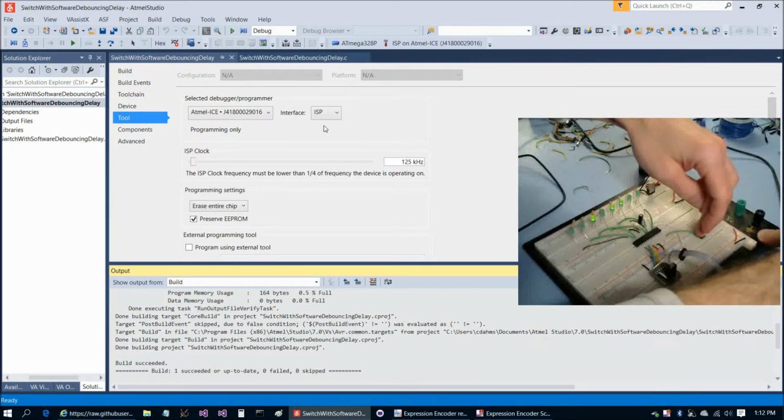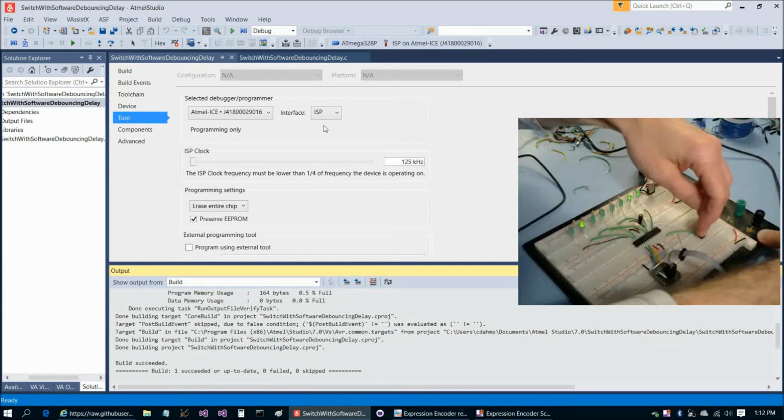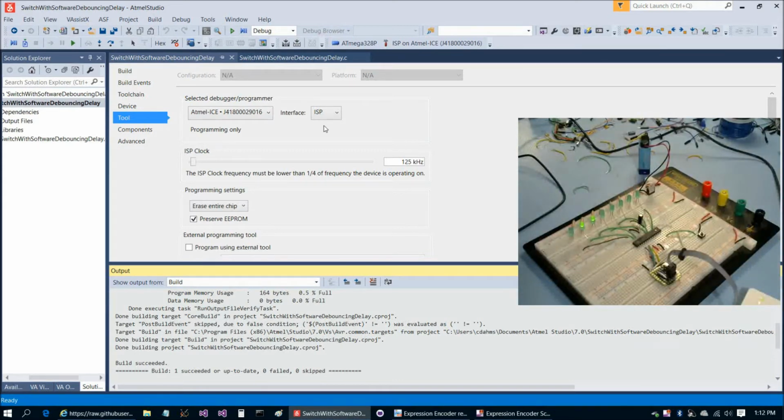So if you're willing to live with a delay, this is a very good way to do it. It is a concern that depending on the switch, the delay may have to vary, and over the life of the switch, a switch that takes a certain delay when it's new, once the contacts are worn, that may slightly change the delay that's involved, so that's something to keep in mind. But if you can live with the delay in your program and it doesn't hurt anything else, this, as you can see, is a very viable way to do it.